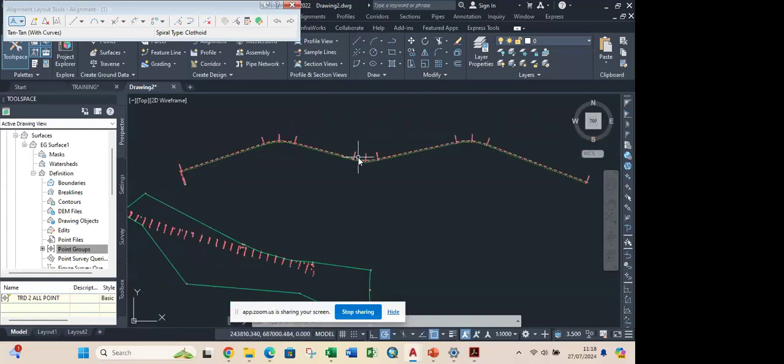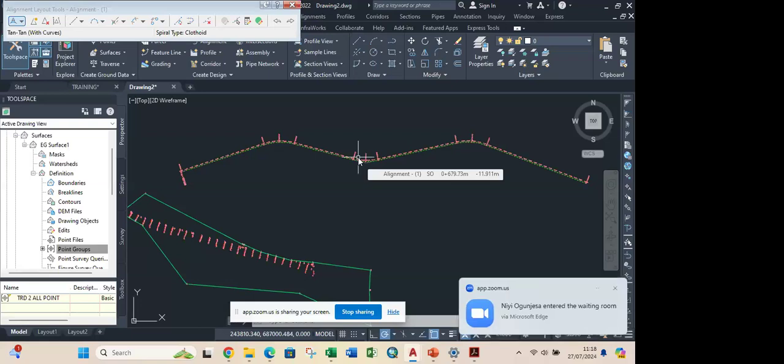So with this first method, there's no leverage for you to play, edit, or shape your alignment to come out perfectly. So I don't normally recommend this first method for beginners doing design. I recommend they use the line tool: use a normal line, draw across a part of the alignment, and when you have a curve, you leave it blank.